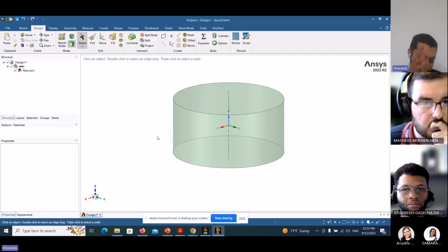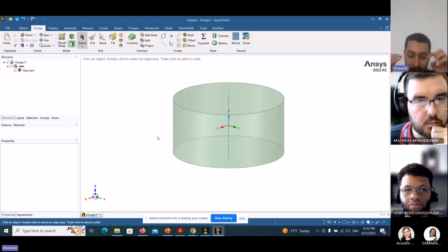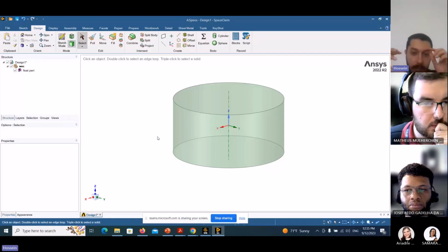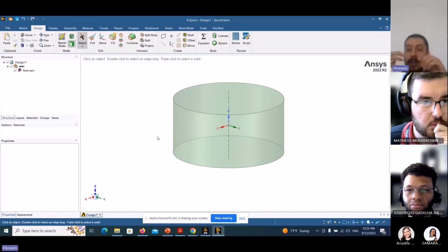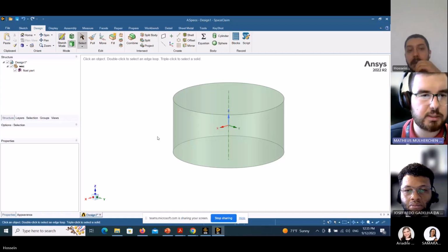About the mass and the mass properties of the geometry, I want to talk about them in the setup parts. But because you asked, the mass properties of the structures in ANSYS AQWA is calculated based on the water density and the wetted surface of the structure, and it isn't related to the density of the structure. Okay, maybe you can do that in a second encounter.